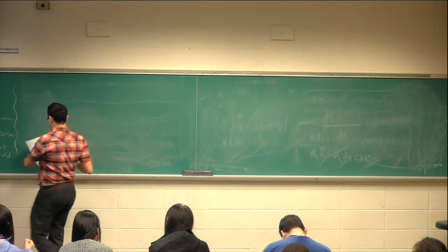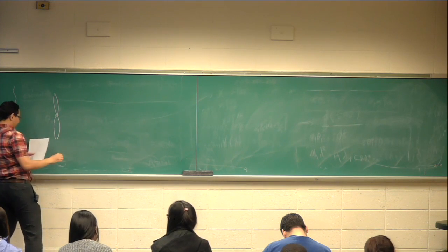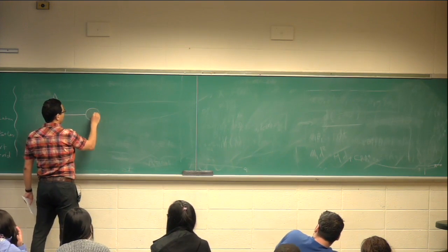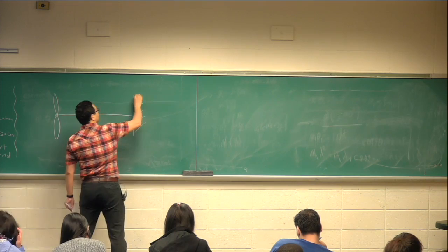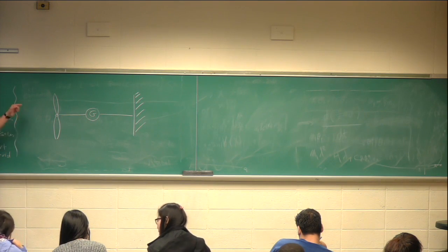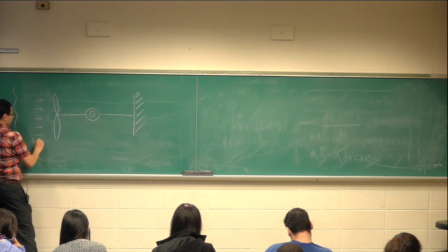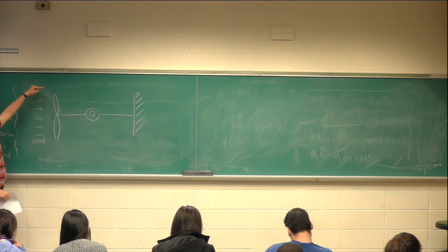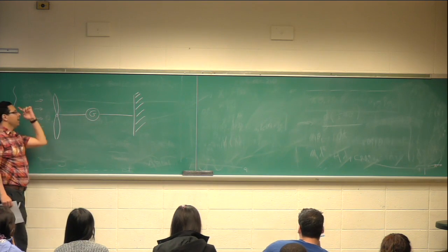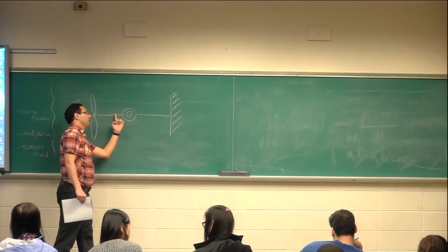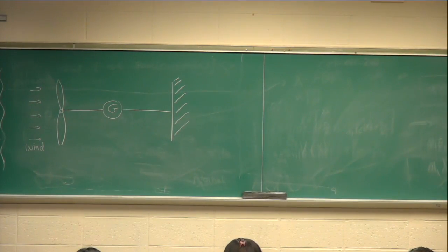So we said the main idea of wind was very simple. You have blades, there is a generator, most of the time an induction generator, which you connect to the grid. On one side, wind is blowing from one direction, this spins the blades, and then on this shaft we get rotation. You might have a gearbox to boost the rotation. Then inside the generator we convert rotation, or mechanical power, to electrical power. Electrical power goes out of the generator and gets into the network.